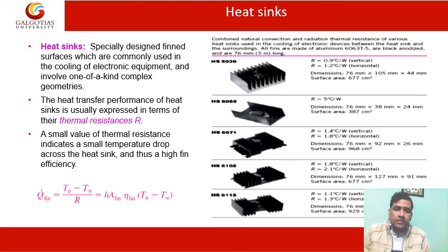So here is the concept of a heat sink, the specially designed fin surfaces which are commonly used in cooling of electronic components and involve one-of-a-kind complex geometries. The heat transfer performance of heat sinks is usually expressed in terms of thermal resistance, which is given by R. A small value of thermal resistance indicates a small temperature drop across the heat sink and thus a high fin efficiency.